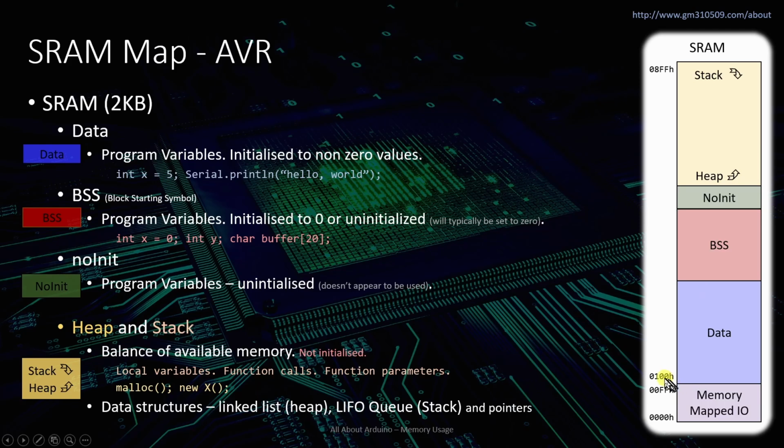So let's say this was 80 hex bytes. There would be a block of memory that's 80 bytes in size in flash that contains the contents of all of these initialized variables, and there's a small section in the startup of the C runtime that copies that 80 bytes, or whatever the size is, from flash into this memory segment. Okay, so it copies it from flash. So this data comes from the flash. This guy, the values that are initialized to 0, there's just a little loop in that same runtime that basically says, starting from here, just make the whole thing 0.